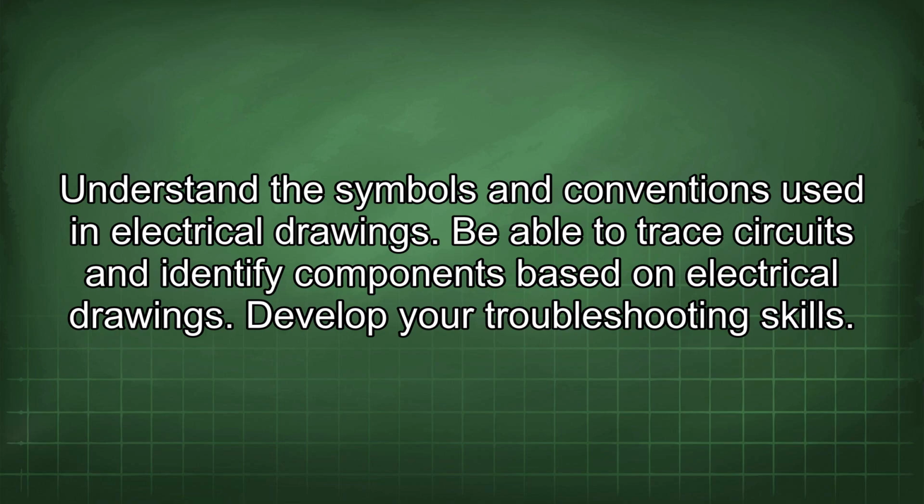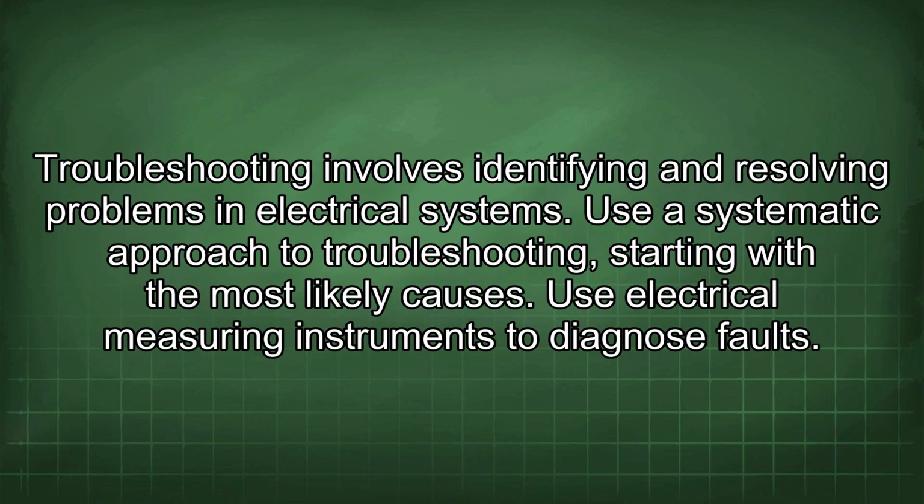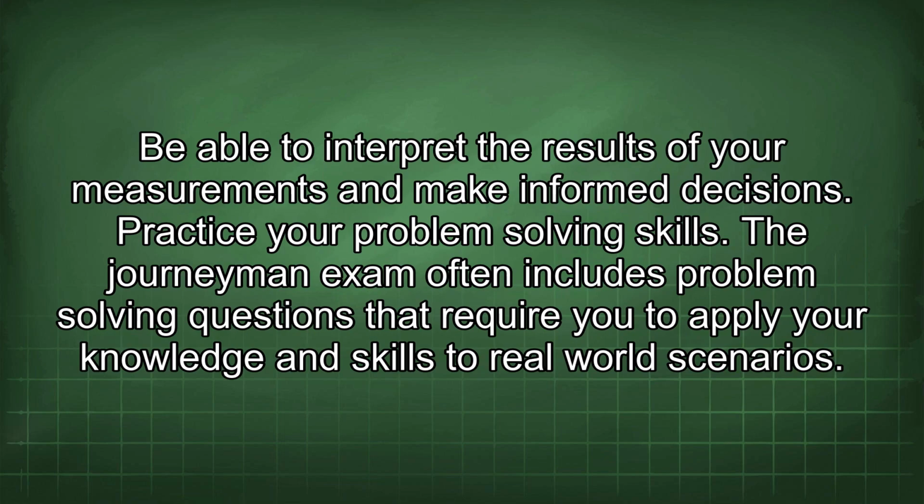Develop your troubleshooting skills. Troubleshooting involves identifying and resolving problems in electrical systems. Use a systematic approach to troubleshooting, starting with the most likely causes. Use electrical measuring instruments to diagnose faults. Be able to interpret the results of your measurements and make informed decisions.